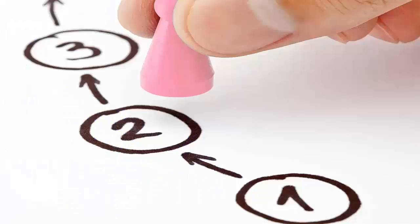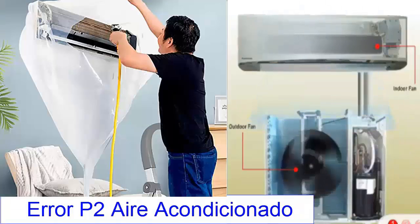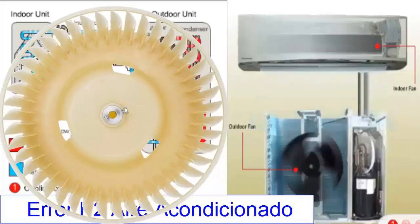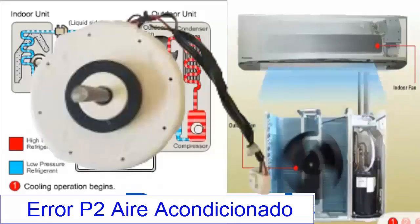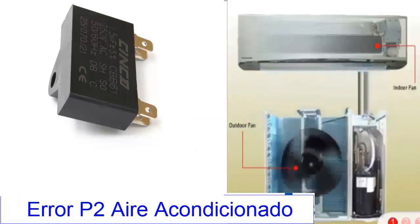In this case, follow these steps to resolve the issue. 1. Check if the ventilation of the indoor and outdoor units is obstructed. 2. Check if the fan blades rotate freely to rule out bearing problems. 3. Check the electrical connection of the fans and if they spin at the correct revolutions. 4. Check the capacitors of the fans.